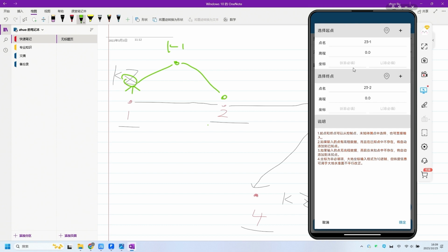If we click on it, it will use the GPS module of your phone to directly locate the latitude and longitude of your current phone position. If you can see my current position, it is actually 34.7226 degrees north latitude, which is our latitude and longitude. If you collect latitude and longitude, everyone must go to the vicinity of the control point. For example, if I measure point 1, I will collect data near point 1. As mentioned later, this latitude and longitude are mainly used for correction.